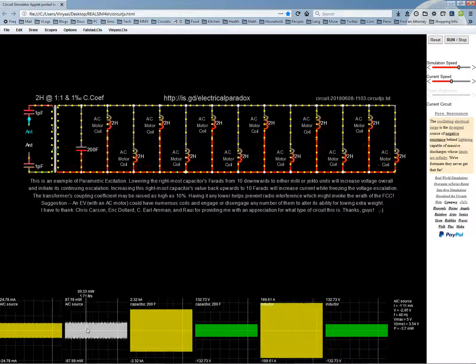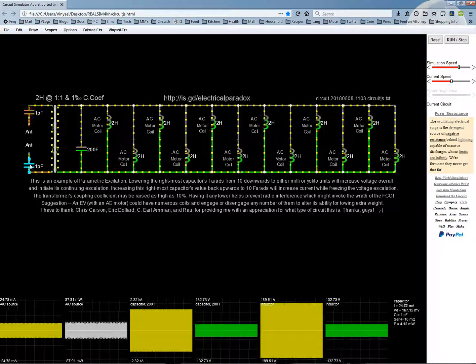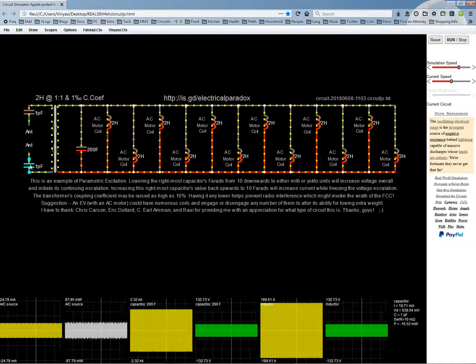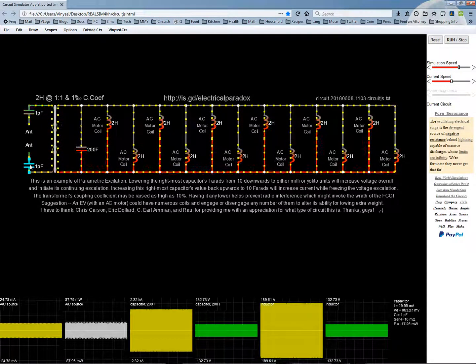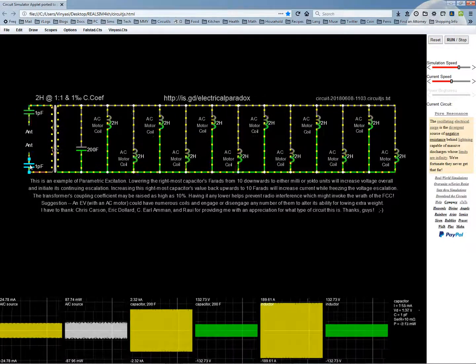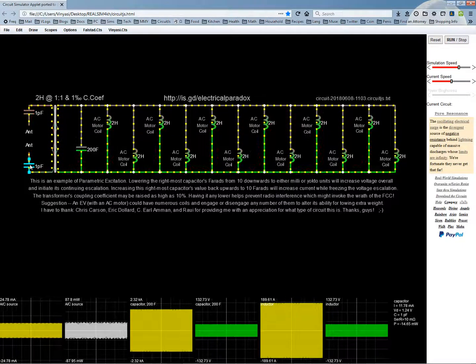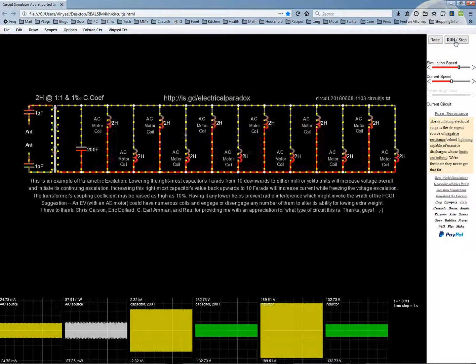Now the wattage is milliwatts. It's still kind of high. I didn't want to go with a lower capacitor, not that it wouldn't help. It would actually help protect the environment from radio interference and the wrath of the FCC. But if I'm only putting out 100 milliwatts, that's probably okay. In terms of short range, it would disturb people's radios, but not over a great distance. So that's still pretty good. Obviously, if a car manufacturer wanted to go to some sort of trouble, they'd want to reduce that further.